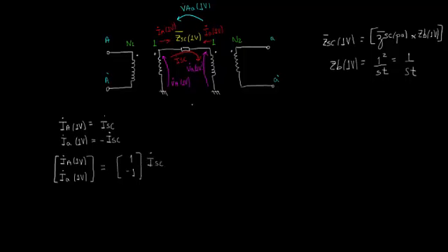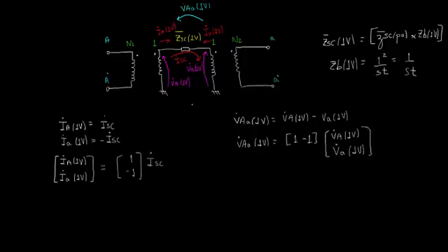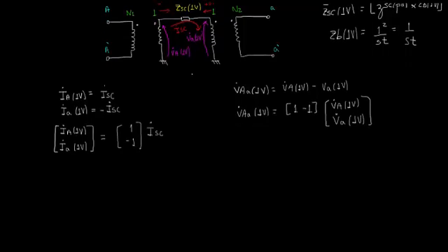The voltage drop across the short circuit impedance is V capital A minus V lowercase a. This relation can also be written in matrix form. The column vector representing the currents flowing in the 1 voltage base windings can be written as I1. The column vector that represents the coefficients that relates I1 and the short circuit currents can be written as B. Then we have the following expression.